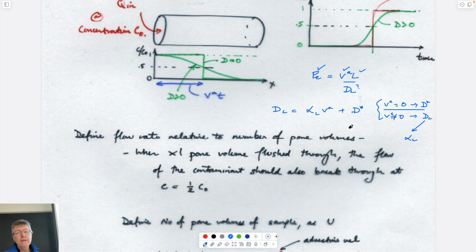But what you'd find is that because this dispersion is a function of two components, right? We talked about this being something that looked like diffusion, but also mechanical dispersion. Since that mechanical dispersion may change, or it seems to change as a function of velocity, then kind of you're exercising that by using a different velocity.